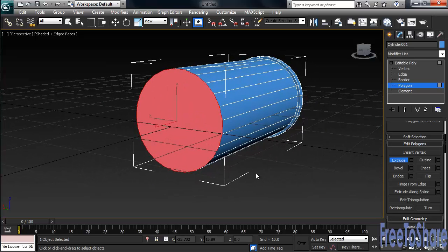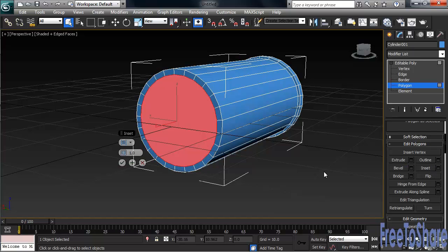To drop down to the next section or level, we'll use the Inset command. Over in the right-hand column, one level below Extrude and to its right, go ahead and click on the option box for Inset. This actually looks pretty good with the way things are, so we'll leave the setting at 1 and we'll simply accept the results.